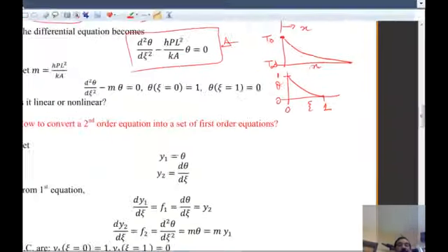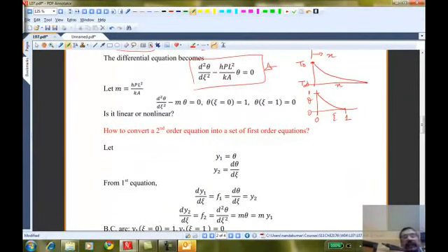We have now formulated the problem in terms of the dimensionless variables, here for the first case, where this is the differential equation, theta is the dependent unknown, psi is the independent variable. The range for psi goes from 0 to 1. We need to convey all this information to MATLAB: what the boundary conditions are, where the boundaries are located, and what the differential equations are.